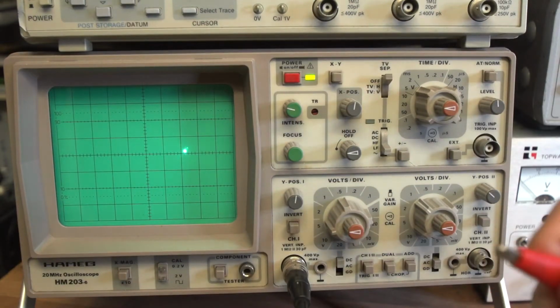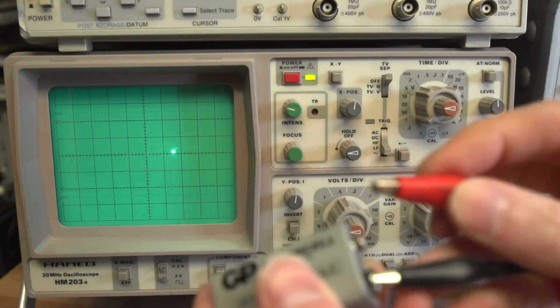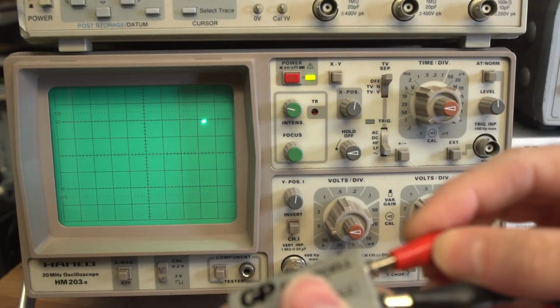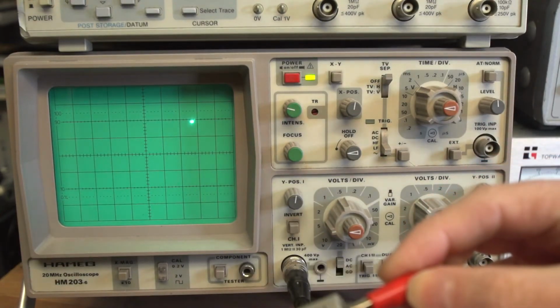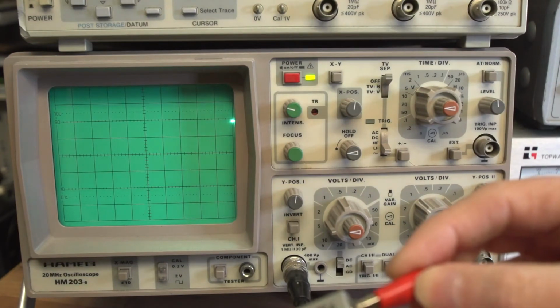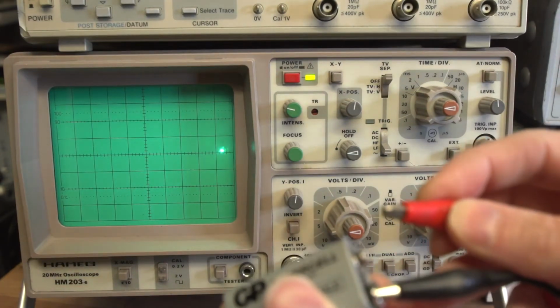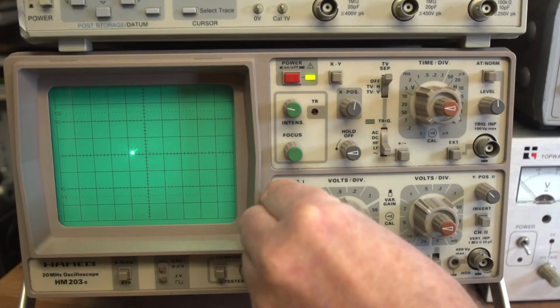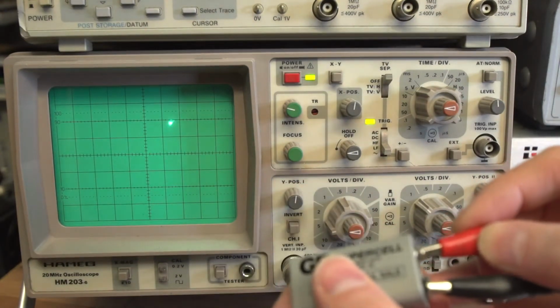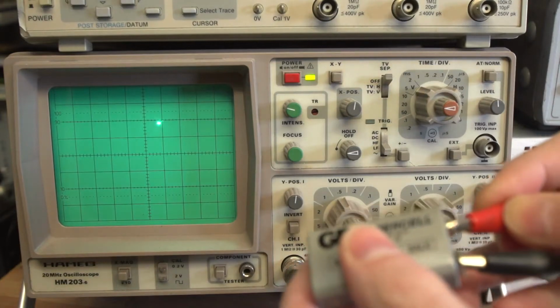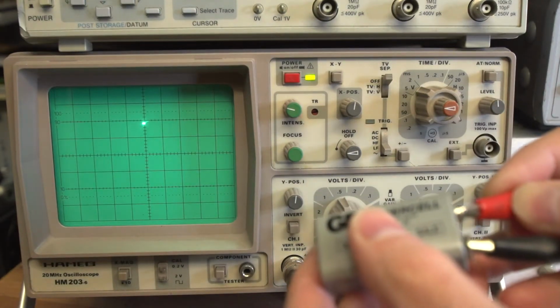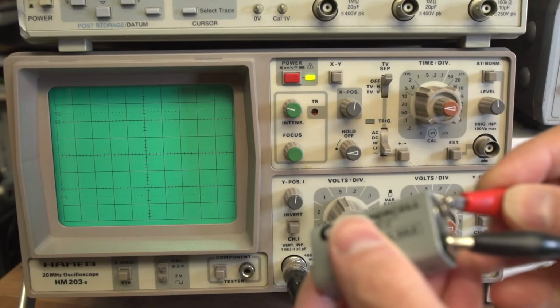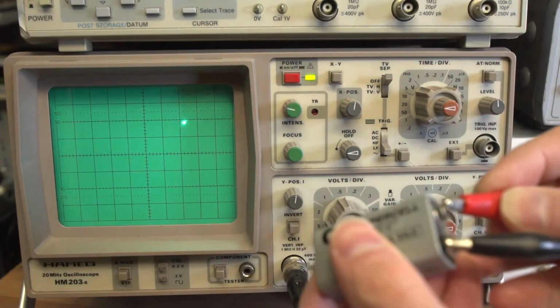I'll just put a DC voltage on here, just with a simple battery. So that's with the power on, with the voltage on. And as you can see, it's exactly right. It's not quite 10 volts. And that's with the battery off. So that's 0. I can probably position that a little bit better. There you go. So that's 0, and that's up there. So that's almost 10 volts, showing us that. And you can use the scope as a voltmeter at that point if you wanted to. Okay.